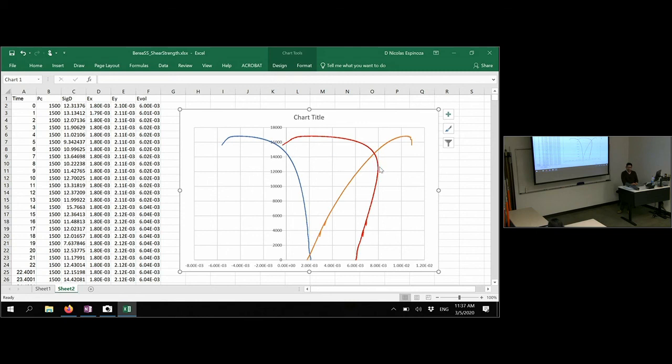And what that means is that at that point, the rock is starting to dilate. It's starting to get bigger. In this region over here, it's not bigger than before, but it is bigger with respect to the smallest size. But in this region over here, the rock is actually bigger than what it was before. And the reason for that is that when you get close to fracturing, some of your fractures may start to dilate as the grains have to go on top of each other.